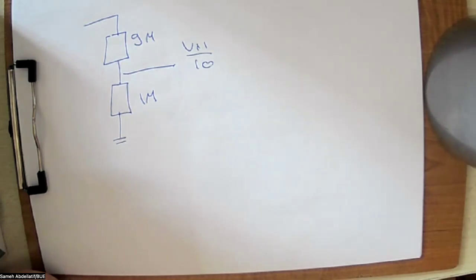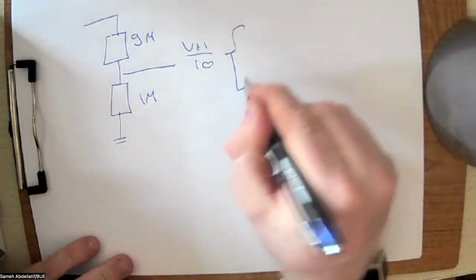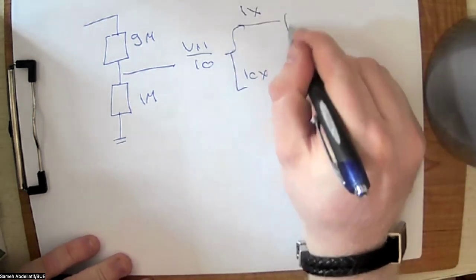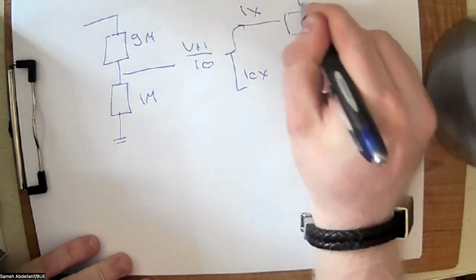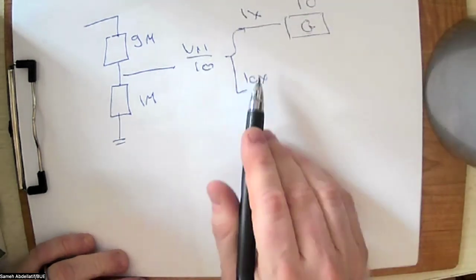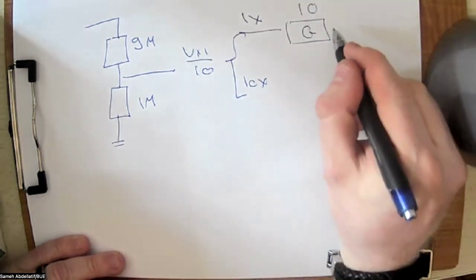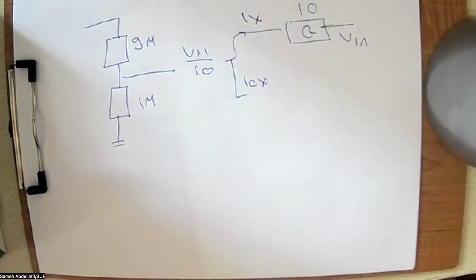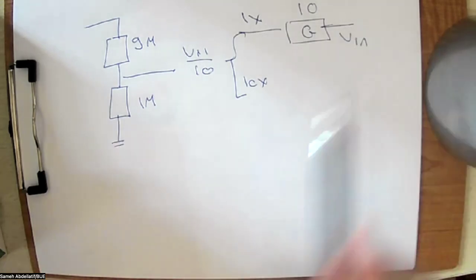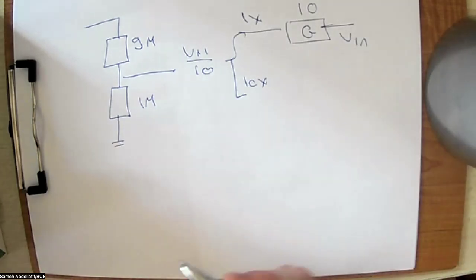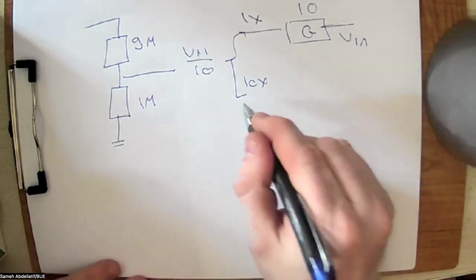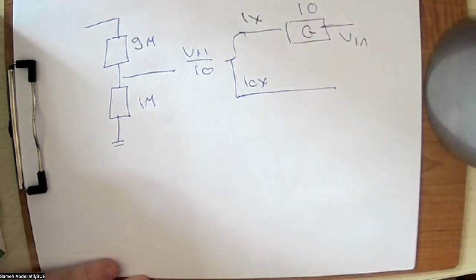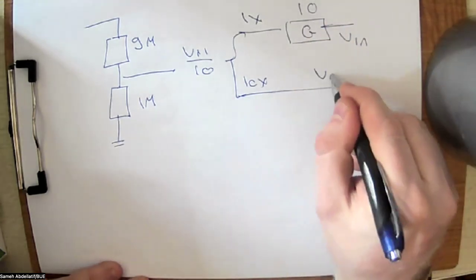In your oscilloscope, you will find two modes, what we call 1x and what we call 10x. In the 1x, we use the divide by 10 again, so this Vn/10 is multiplied by 10 again. So what you restore here is Vn again, which is the normal mode. Usually, when we work with the normal mode, we have this value. But the oscilloscope offers another mode, which is this mode. So here, what you get is Vn/10.